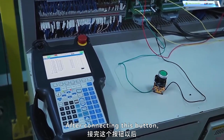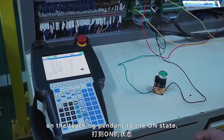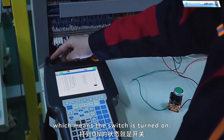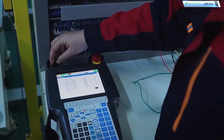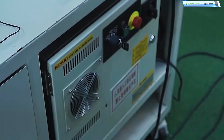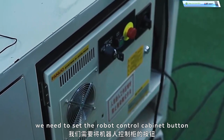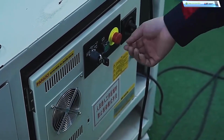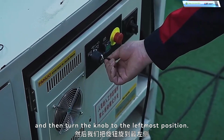After connecting this button, next, we need to switch the mode on the teaching pendant to the on state, which means the switch is turned on. Next, we need to set the robot control cabinet button to automatic operation mode, which is the auto state, and then turn the knob to the leftmost position.